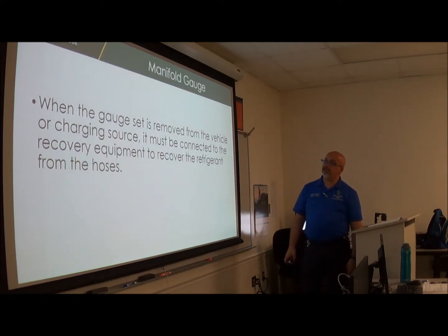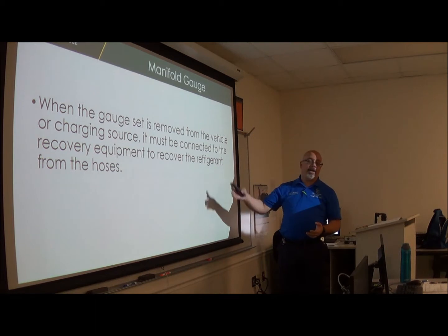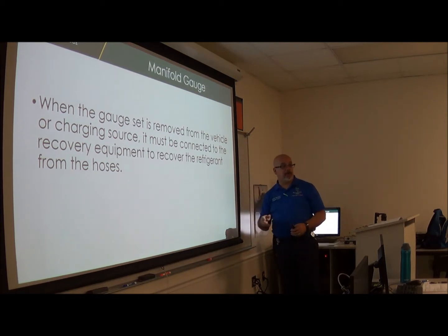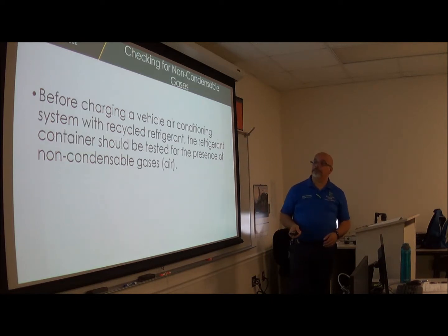When the gauge set is removed from the vehicle or charging source, it must be connected to the recovery equipment to recover the refrigerant from the hoses. One of the most common things that we see in all the repair shops is that they disconnect the gauges off the car and they do not empty those through the vacuum system. They just hang them on the wall or whatever, and it still has refrigerant inside. Okay. So the law requires that you do a vacuum also on those hoses. Okay? That makes sense.